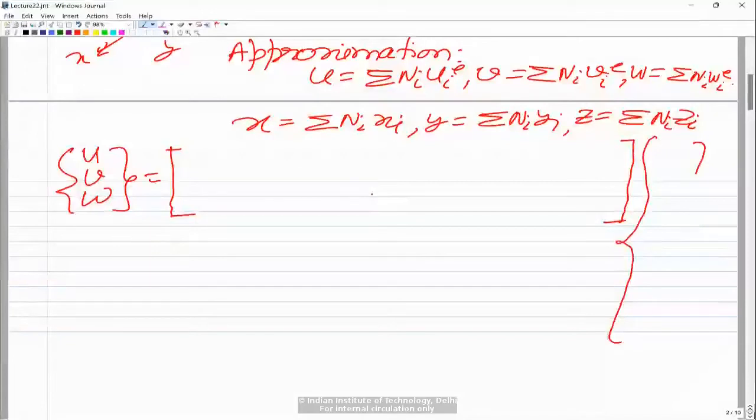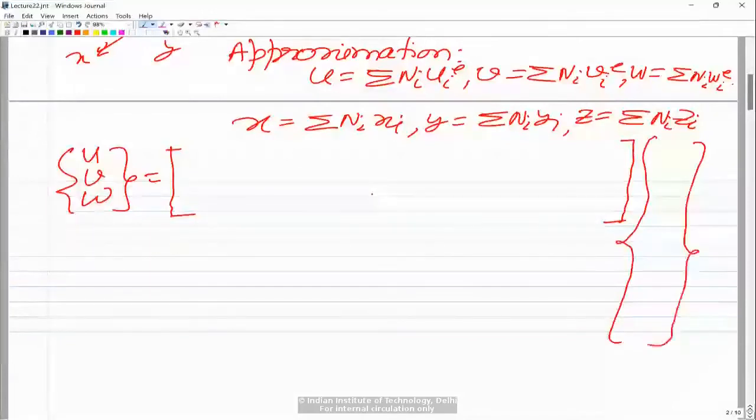Now at each node, when you are talking of a 3D solid element, there are 3 degrees of freedom per node. Those degrees of freedom are basically displacements along three orthogonal coordinate directions x, y, and z. So for each node we have 3 degrees of freedom, and since this is an 8 noded element, for the element as a whole we will have 24 degrees of freedom.